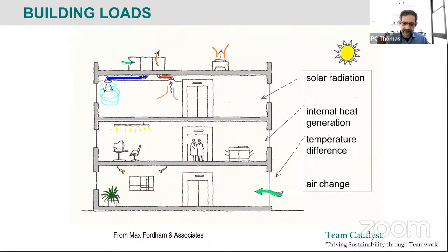And the other one is ventilation air, or the amount of outside air you bring into a space to provide oxygen and to make sure that people don't get sleepy, and so on. CO2 concentrations you want to reduce, okay? So those four things we're going to have to set up first before we can do the load calculation.